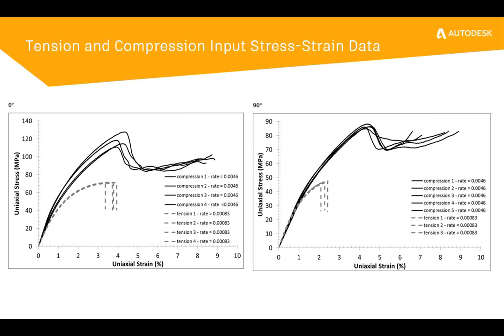Now this is vital because look at the difference in the stress-strain behavior between when we're pulling our plastic in tension versus placing it in compression. What we see is the initial stiffness is the same. You know, that's what we expect. We expect that initial stiffness to be the same in tension or compression. But we see two things happen. With the tensile behavior, plasticity occurs and evolves much more rapidly. Those curves start to bend over much more rapidly than they do in compression. The second aspect is that the failure stress is much lower in tension than in compression, almost half in this case.